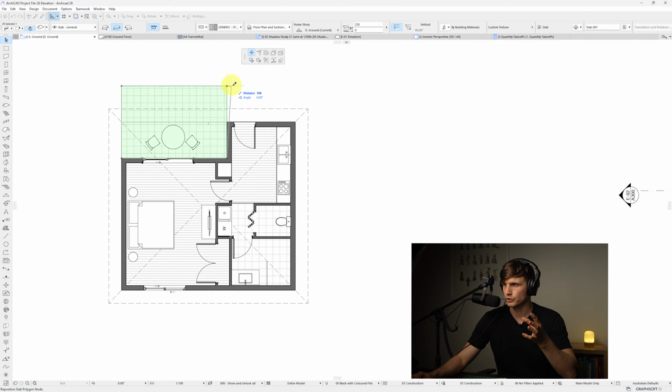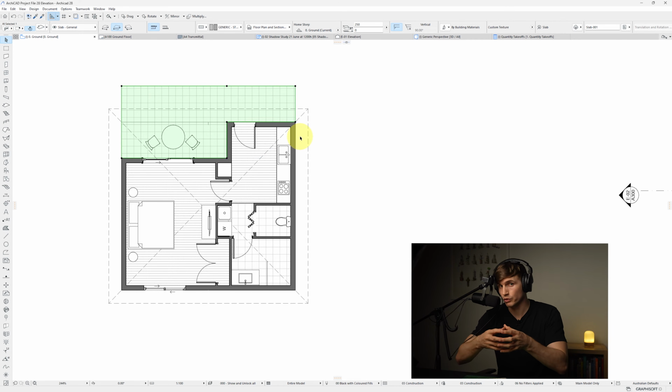From here, we want to add to the slab just in this area here. So we'll select this corner node and then we'll go to add polygon, this one just here. With the geometry method rectangular selected, we'll go from this top left and drag it all the way to this bottom right and click once. And we've now extended that slab across the frontage.